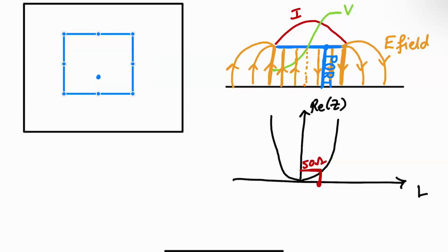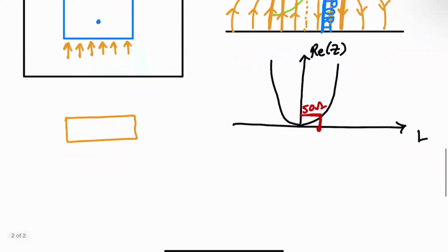So those fields look like this, electric fields. Right, you have one there and one down here, right? So this should remind you of a slot, right? A slot also has electric fields that are like that. So really, you can model this patch as two slot antennas that are separated by around lambda over 2.